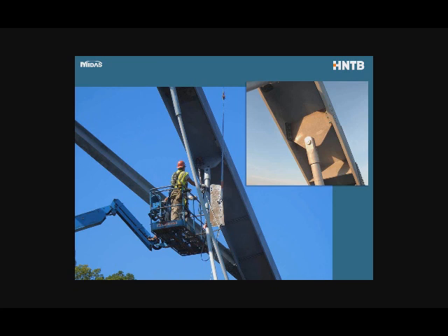And then the final step is the whole cable is lifted in place, as shown here. And then it's very simple pin connection, just like what you've seen for the Happy Hollow Bridge. So with this system, much less work for cable connecting, but you need much larger equipment to stress if you have large cables. And of course, you have to deal with the weight of the cable, and if you have to replace the entire cable.